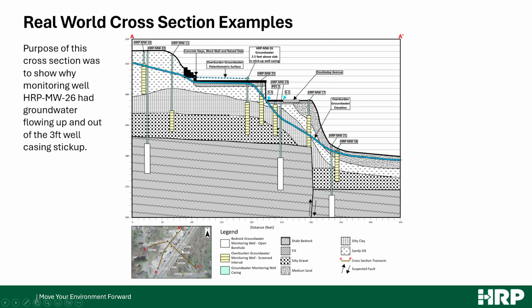The surface elevation of the road is approximately 15 feet higher than the parcel that's immediately to the southeast of it. And our offset in bedrock matched the expected offset you would see with this fault system. So we were able to put a bedrock fault within our cross-section to allow us to explain why the bedrock changed in apparent depth from the surface. So this was one of our more complicated geologic settings.